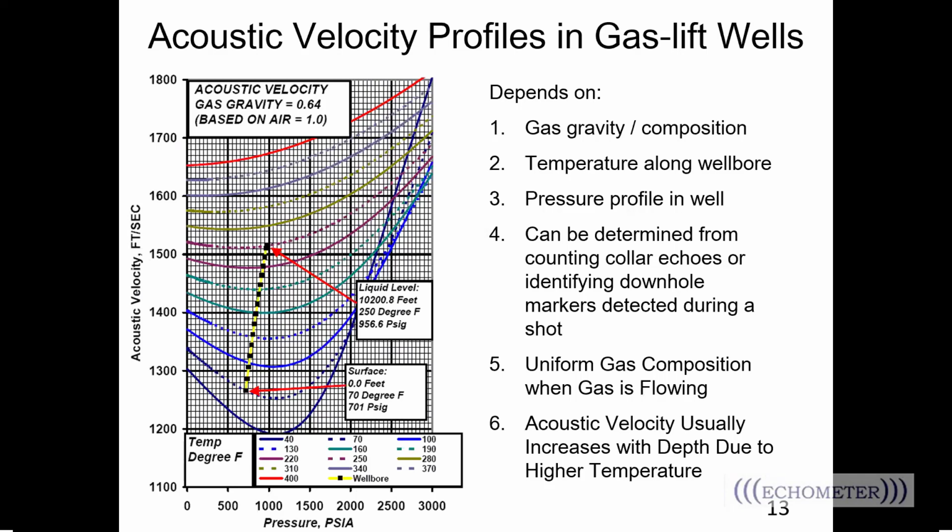A lot of times we will have wells where the static surface temperature, say it's 70 degrees, will eventually meet the flowing gradient, but the flowing gradient might have a surface temperature of 170 or 130 or 140 degrees. Right. And the problem that we get into, as you can imagine, is what do they design the gas lift design to, right?